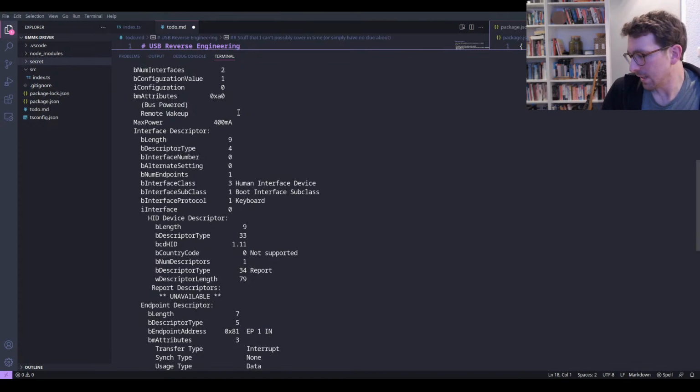And this is also why I've had problems in the past when I've used this keyboard in a hub in one USB port with a bunch of other devices attached, because Apple don't want to put proper USB ports on their computers and make it really difficult. I've had times where if I've plugged too many devices in, not everything stops working, and that's because collectively everything is asking for more power than that one USB port can provide. A regular USB port can only provide a fixed amount of power, and that varies between the different standards, and it's not that important for now, but it's something to keep in mind.